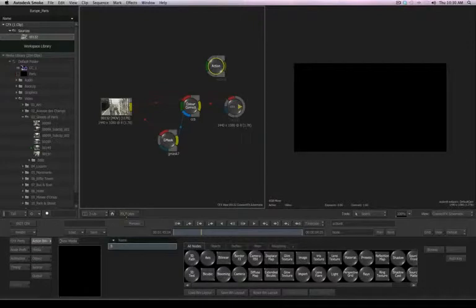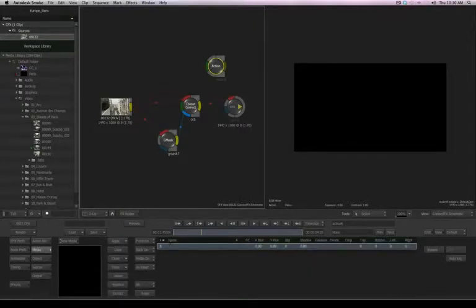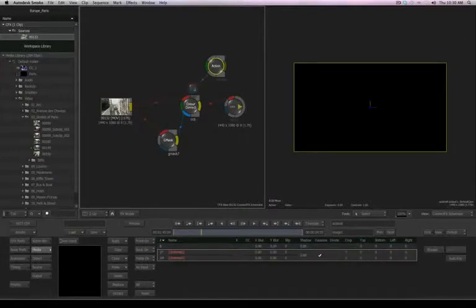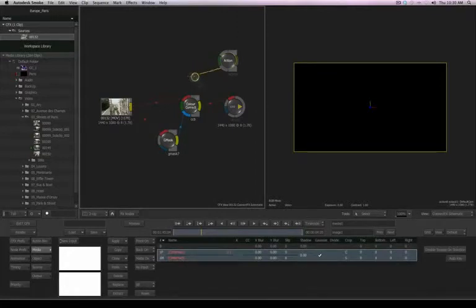Let's discard our node bins once again so we can see the action parameters. On the Media tab, you'll notice in the Media list, again, as I said, all I have is a background input. I want to add another input to this. So if I come over here where it reads New Media, I can click and hold that. You'll see the option for New Input. When I choose that, in the schematic, you'll now see a new input is available to me here. And again, looking at the node, we see there's a red input for our front and a blue input for the matte. The same shortcut hotkeys and connection methods work with the nodes for your layers in Action.